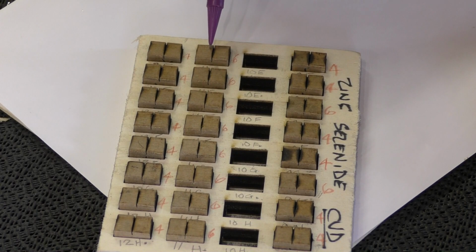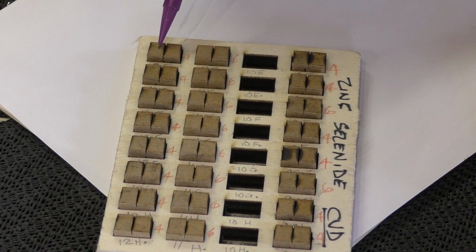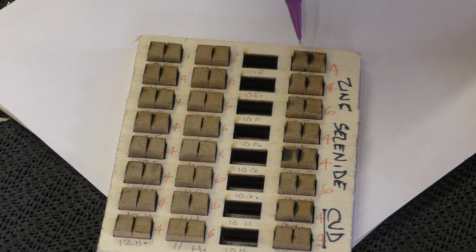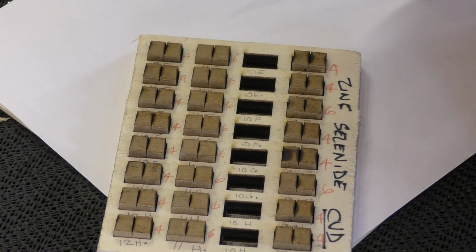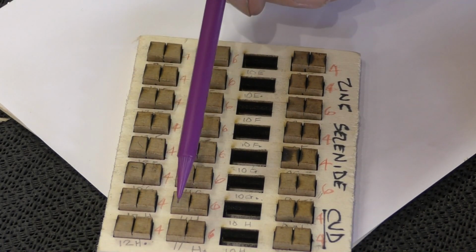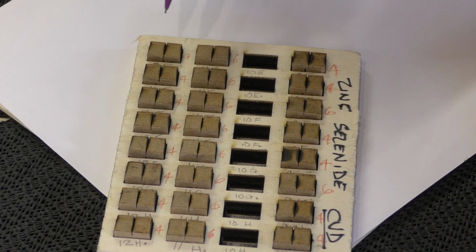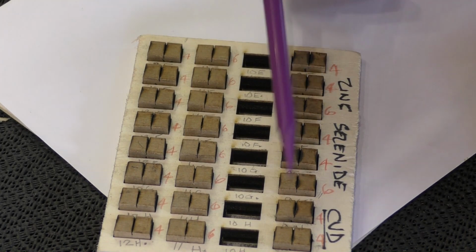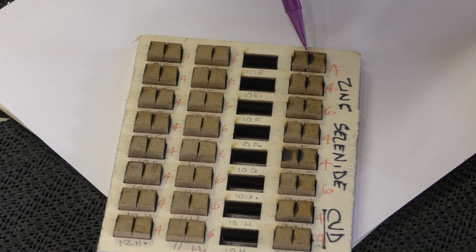The same applies to the 2.5 inch lens and the 4 inch lens. There's a slight difference in the beam thickness and the line thickness, but that's not the point. The point is we're producing parallel sided holes. Now, passing through 10mm, which you certainly wouldn't want to do with a normal 1.5 inch lens, that's absolutely staggering. So today we're going to try and see if we can find out what's going on inside the cut.